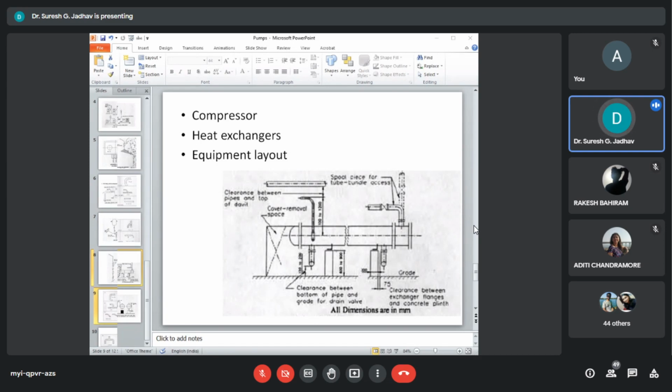Heat exchangers should be close to the other process equipment in case of draw of flow through an exchanger from a vessel or reactor bottoms. The exchanger should be close to and under the vessels or reactors to have short pump suction lines. Overhead condensers shall be placed above the reactor to handle flows.